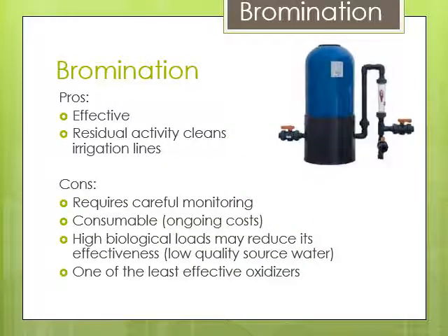Bromine is definitely effective, though. It has a residual activity, which is great. That means that you add it at a point. This is what a bromine doser looks like. It goes out into the greenhouse, and it is continually sterilizing the water as long as there's biological activity until it's all used up. It does require monitoring.